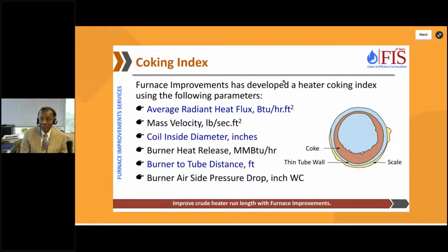We have designed heaters for 8 years run length of crude and vacuum heaters. We did it for a refinery in Lake Charles. And it worked for 8 years. So basically, the coking has never been talked about during the design.